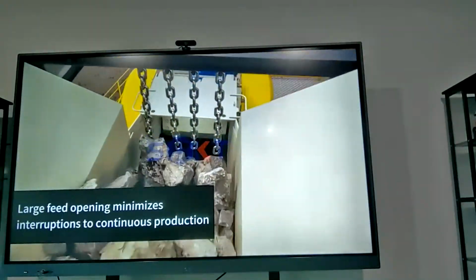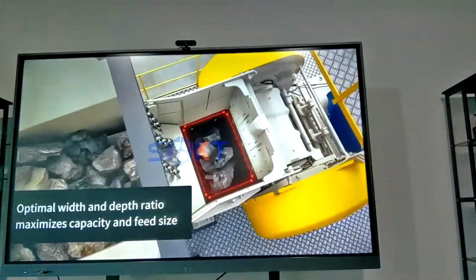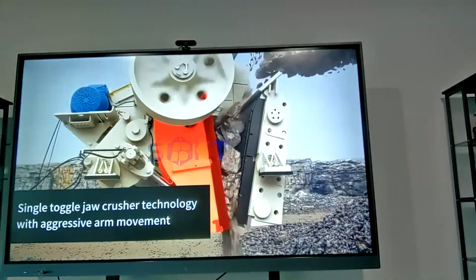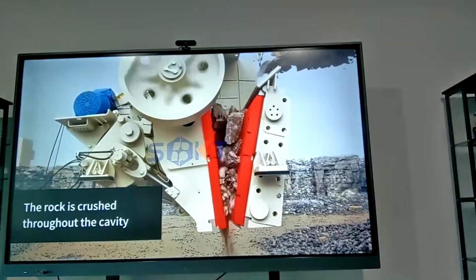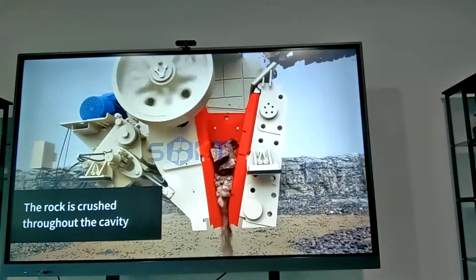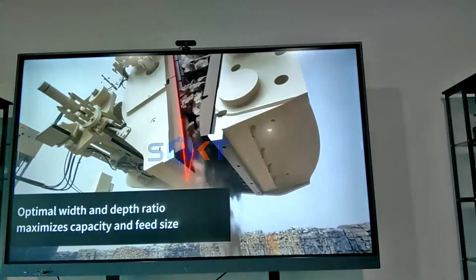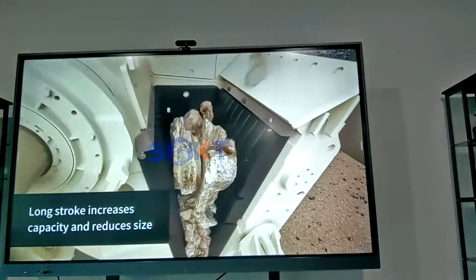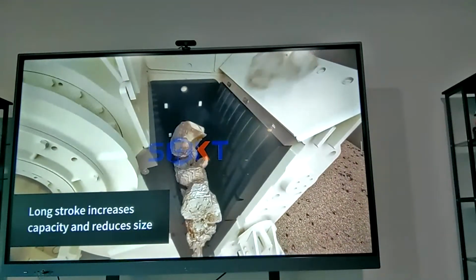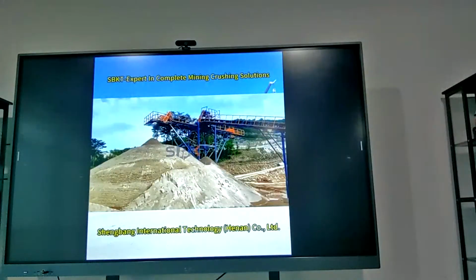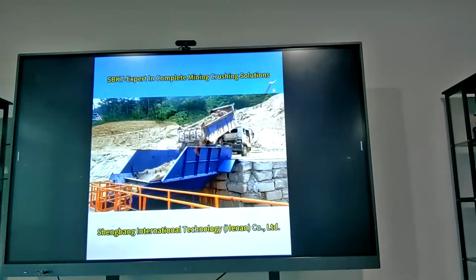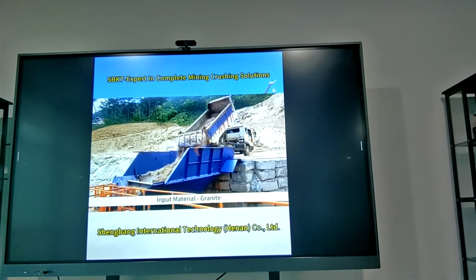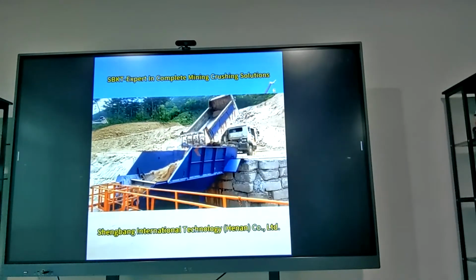For the European version jaw crusher, the hydraulically adjustable discharge port and locking spring safety device enable precise control through simple operation, which reduces the frequency of manual intervention, simplifies the maintenance process, ensures the uniformity of the discharge particle size, and is conducive to improving production efficiency and product quality.